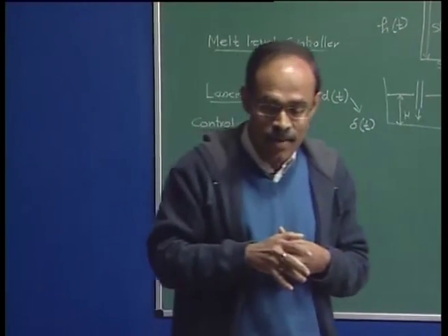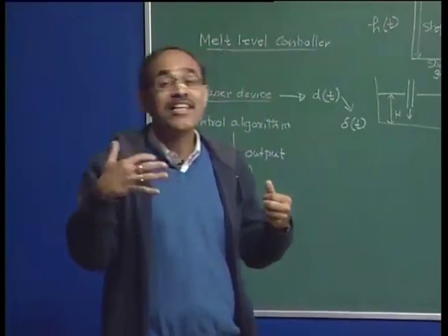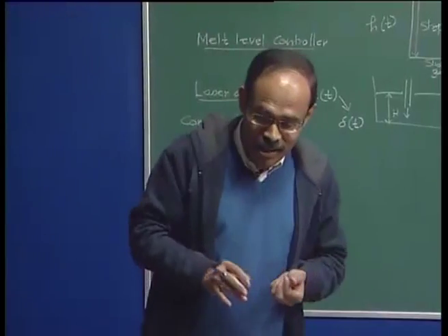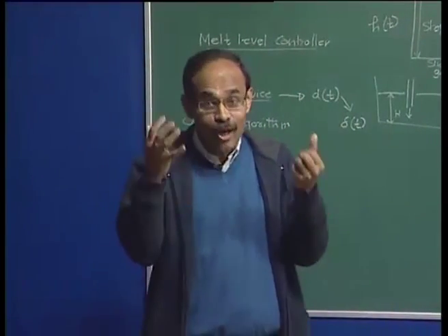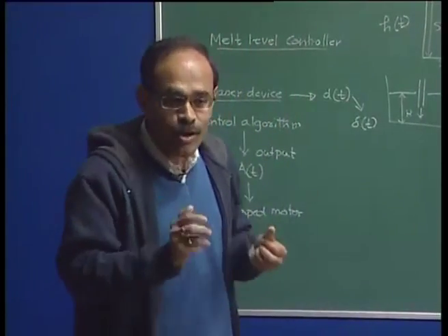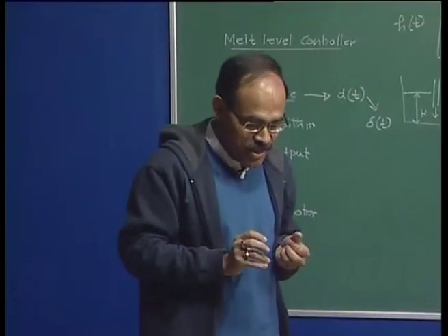through continuous casting. And then comes the tundish, which we have traditionally seen as a buffer vessel, but now, whatever I have discussed in the last few lectures, we have seen that there is a lot of scope to improve the quality of steel further in the tundish, and also ensure defect free cast products coming out of the continuous casting process.